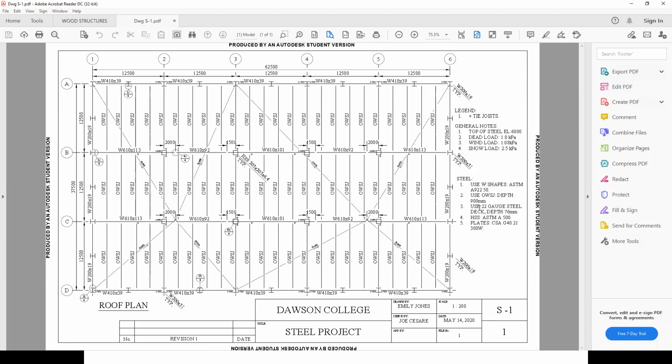So here, for example, instead of the 38mm deck we decided to use, they had to use a 76 because the spans here were fairly high, and they ended up using a 900mm depth joist, whereas I think we decided on 650 for you guys. And then of course, this is the steel that you're going to be using for the W shapes, and then you have to specify the steel for the HSSs, which they didn't do here. Yes, she did specify the HSSs.